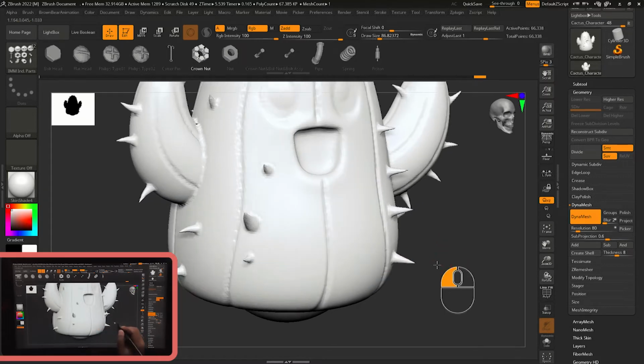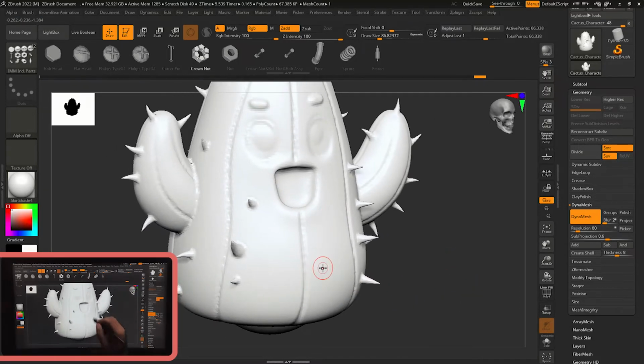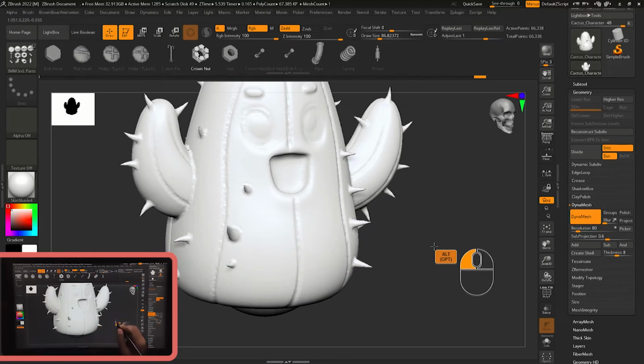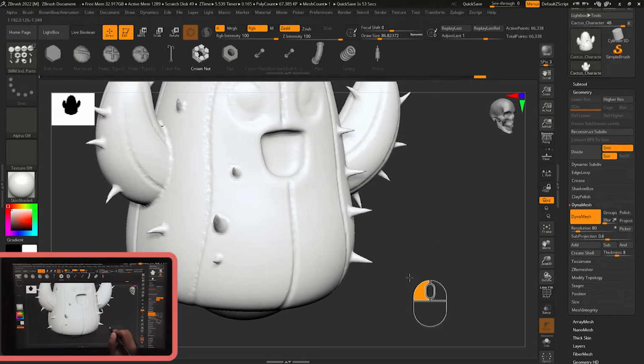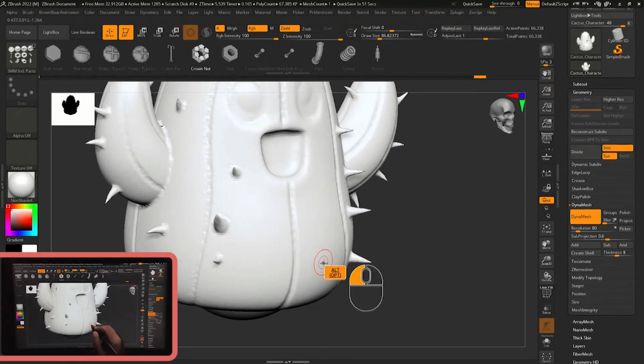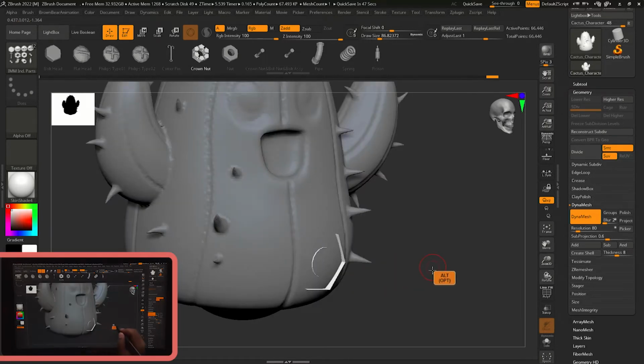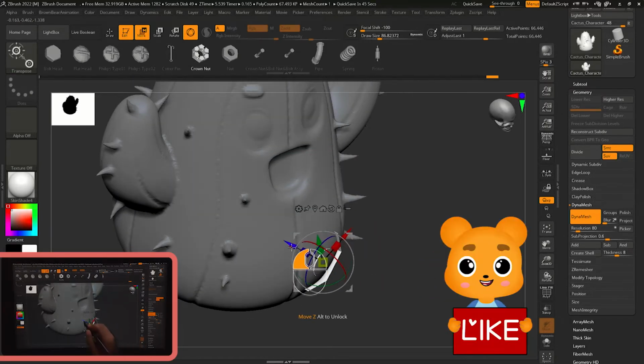It's very simple. It's something like this: we have two meshes and we have some operations, like we have to add those meshes, subtract those meshes, or we can get the mesh which is in between, the intersection. In this example, I will explain it to you. I have this IMM brush and I will just hold Alt and drag that mesh onto the model, and you will see this is a negative mesh.